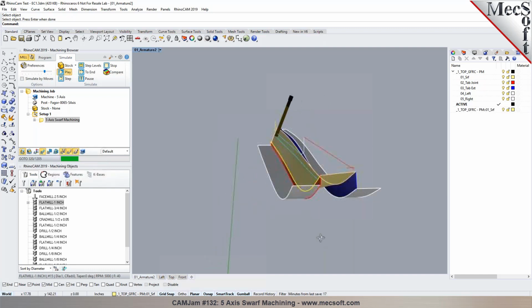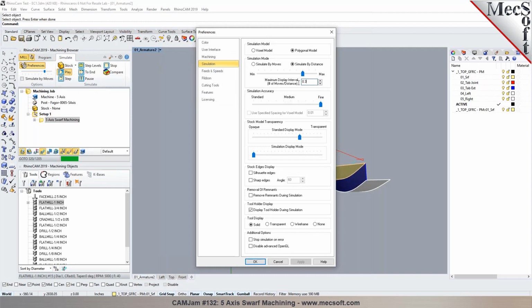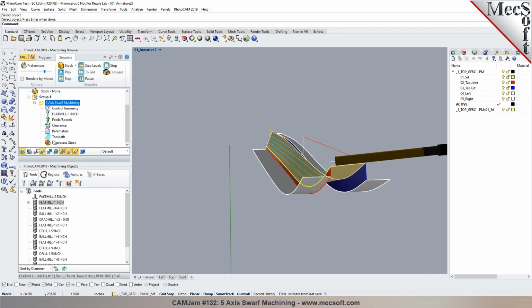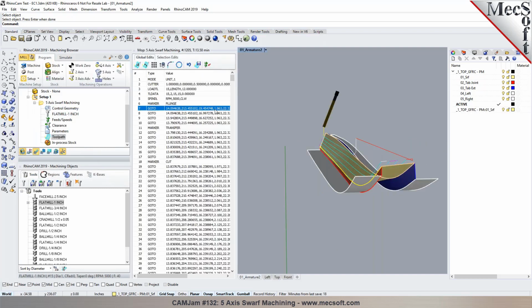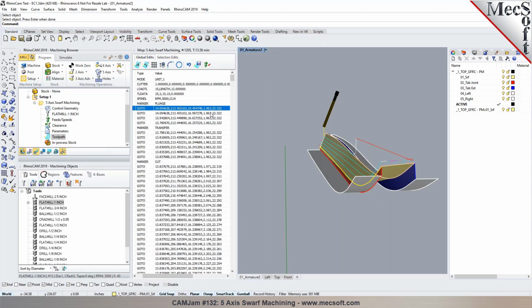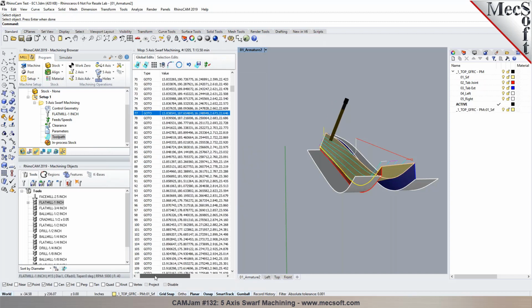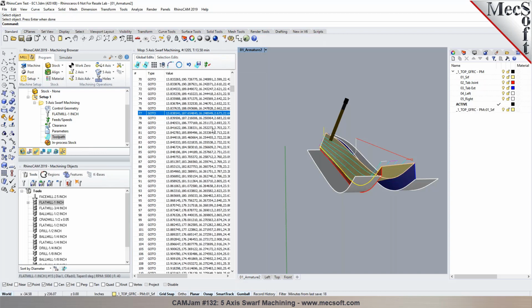So I'm just showing you the animation in here. I can even speed it up. I can just increase this distance in here. And you can actually see the angles right in the cutter location. We call it the CL file. So that shows your angles in here, primary and the secondary. That's where it's starting. That's your XYZ, and then your primary axis, and then the secondary axis. And if there's crossing the limits, it'll mark those in here during the toolpath itself.